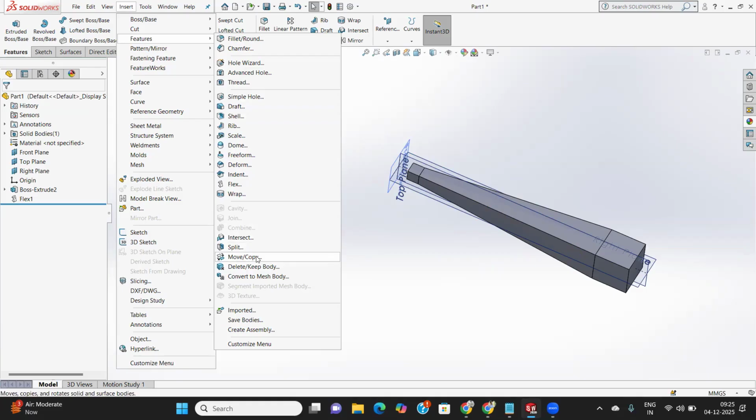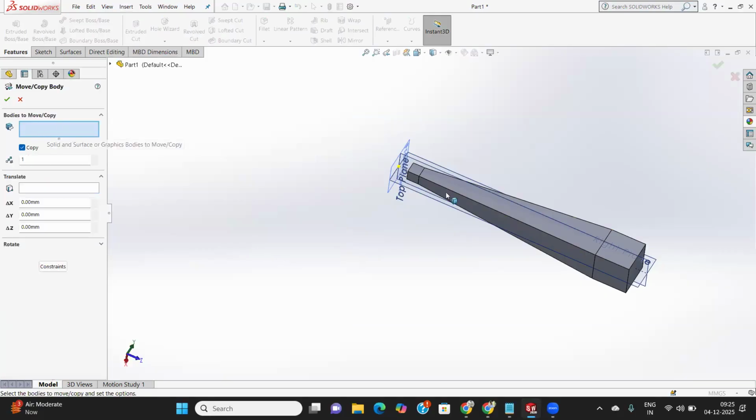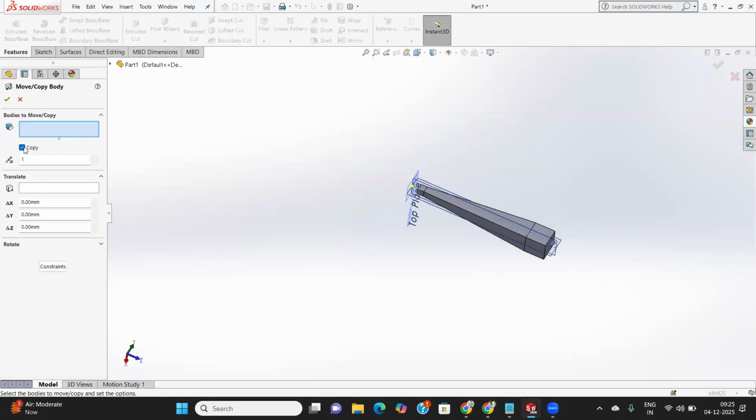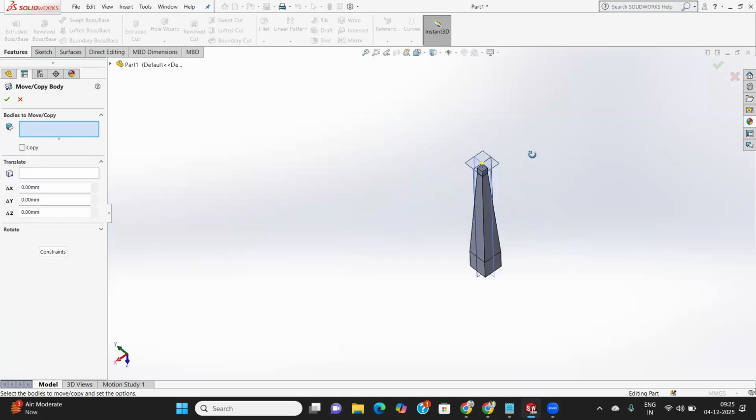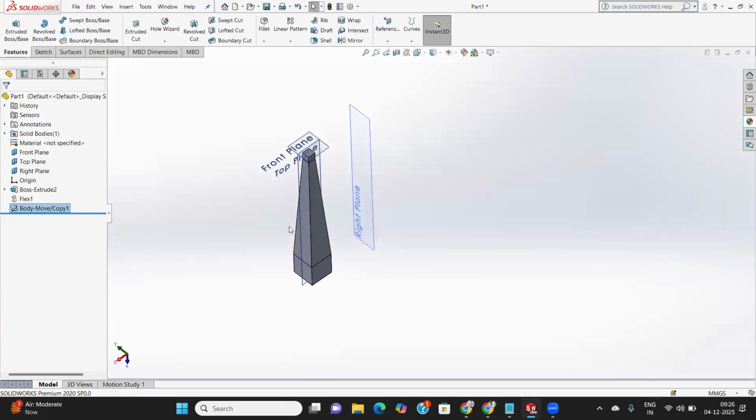What's the move and copy is to? Cut and place. If you click on the move and copy option, there we have the move it and then copy it. If you want to move the objects one portion to other portion, just what you do, click on it and select it, and then which direction you want to move it. Okay, X. Just click on the mouse button and move it in any direction right there, and then click on OK. Then your punch is moved, right?